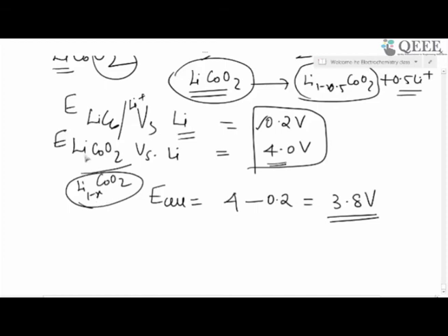During charge, lithium will be taken from this and deposited in the lithiated graphite. So this is going to be the reaction in the lithium battery. This battery gives typically about 620 watt-hour per liter of volumetric energy density and an energy density of about 250 watt-hour per kg.